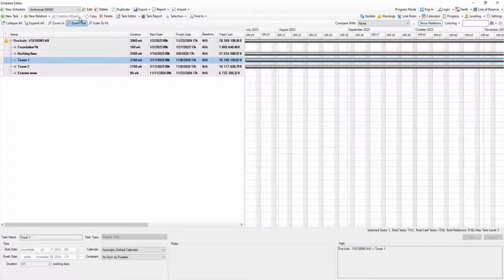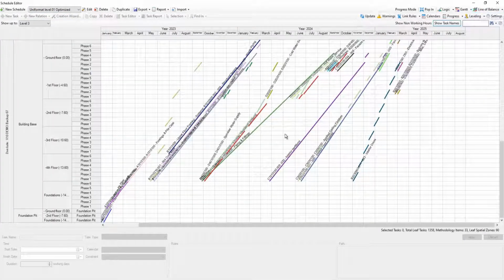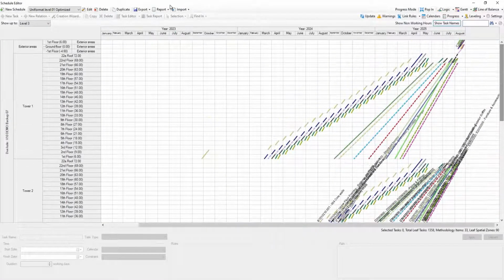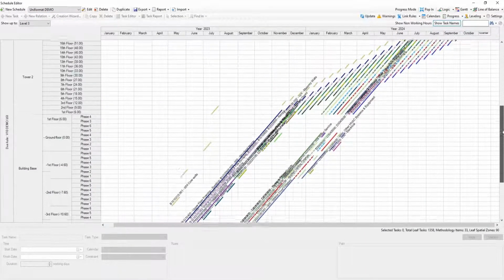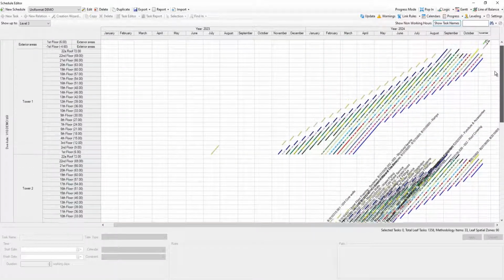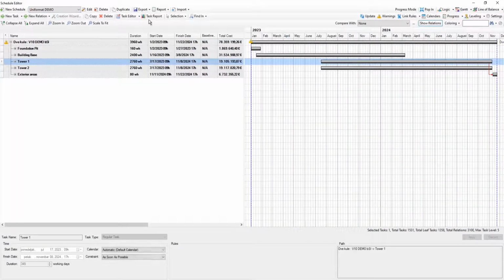And the most important thing with the task report, since, as we said, the schedule is connected to the cost classification, we have the ability to assess the quality of the schedule by simply checking the line of balance view, where we can optimize the schedule, as in this case. This is the same schedule as we have created, just optimized for roughly an hour and a half, not more than that. So we can see the striking difference from optimization of the schedule, just changing durations and changing some constraints.